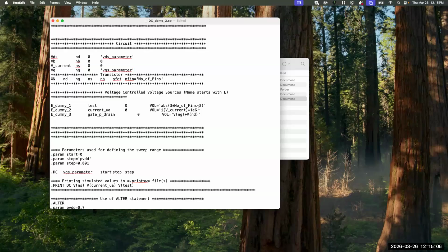And because of a mistake, maybe you misspelled something. Just notice how easy it can be to mess things up. Instead of number of fins, I write number of fin. So it doesn't recognize the parameter. It doesn't pass anything, but it assumes the default parameter. You see my point here? Somehow I made a mistake, or I led to a situation where the parameter was not really passed down to the deeper level. So at some point, it will just assume the default value and run with it.